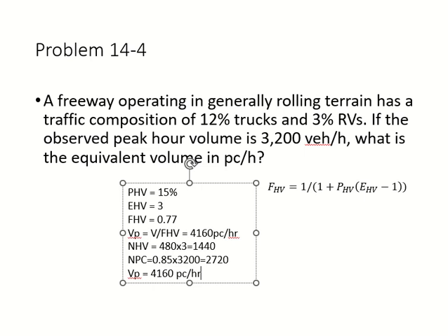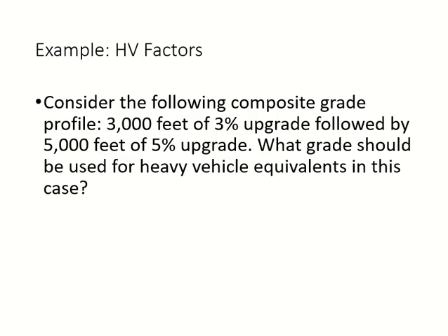Okay, they should be equal, right? Clear? So you can divide the entire volume in FHB, or you can take the heavy vehicles separately, multiply by the equivalency factor, and then add the cars. Clear? Okay.